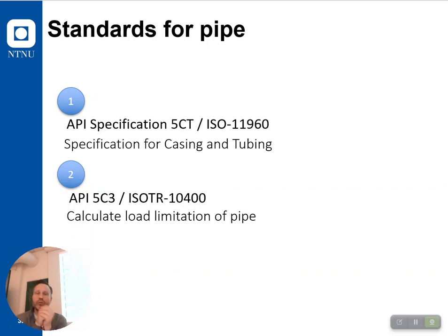And of course, you can't over torque the threads. The threads have to break at a certain torque, otherwise you have to rethread the pipe. So even if you lost more than 20% of the thickness, you can still use it? No, then you can't. The limit of wall loss is 12.5%. Otherwise, you're in a different scenario. You can't use these calculations anymore.